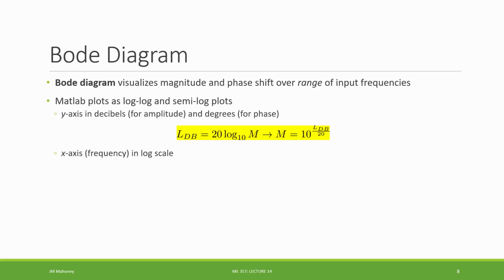And we're going to see that the frequency, I'll actually start at the bottom here, is going to be in log scale by default. So it's going to be 10 radians per second, 100, 1,000 as our scale. And we'll see in MATLAB how we can get our exact values out of it. And then for the top graph, the magnitude graph, the magnitude by default is going to be expressed in decibels.